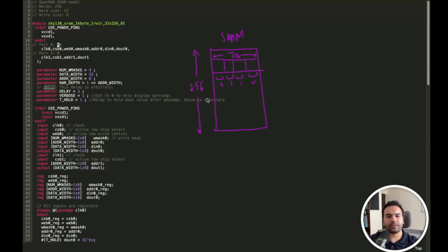If we take a look at the write mask width, it is actually a 4-bit signal, which means they are utilizing 1 bit for each of these columns. So if, let's say, we only want to update this particular entry in the SRAM, we could assert the mask bit for all of the others, but deassert it for this particular entry.